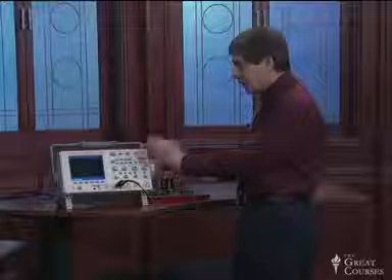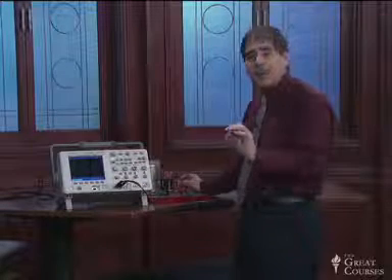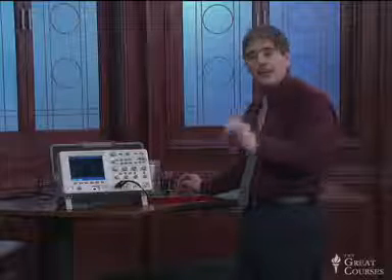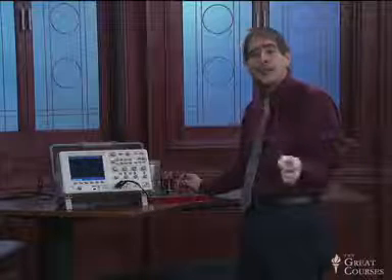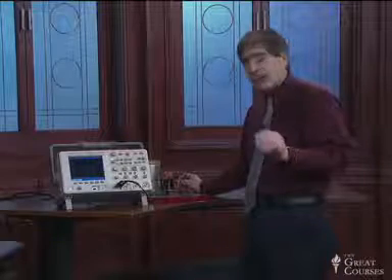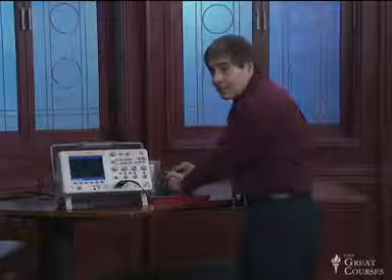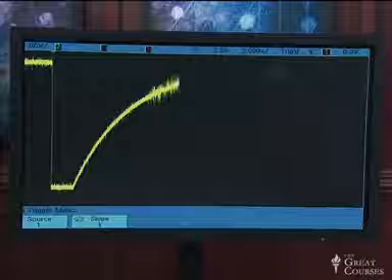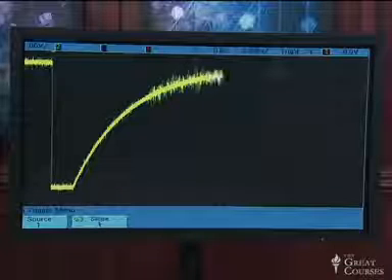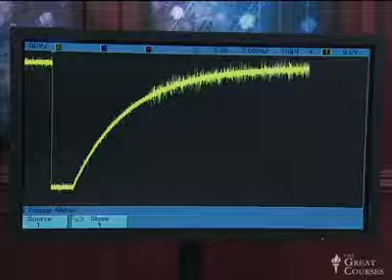And so I'm going to start the oscilloscope going. I'm going to discharge the capacitor, and then I'm going to take the short circuit off the capacitor and let the capacitor start to charge, and we'll see that characteristic curve showing the slow rise of the voltage as charge begins to build up on the capacitor. So here we go. And there we go. The curve is rising with an ever-slowing rate, rising with about that 2.5 second time scale. And here we go, going toward that level of 6 volts.